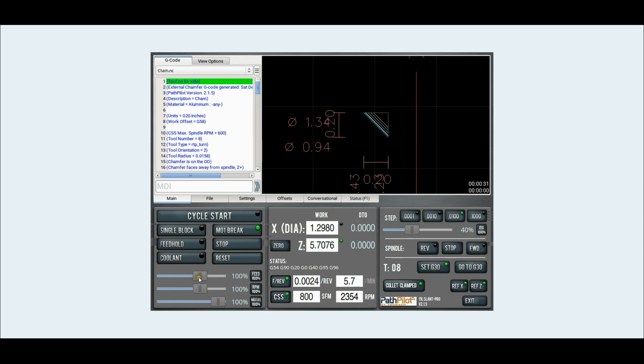So the feed is the actual cutting speeds and such. A lot of times I'll drag that to 0. I'll drag this down to 2% or something when it gets close, and then it'll basically just stop. Once it finishes the rapid move in, it'll just stop before it starts feeding in, because the feed will be set to 0. That way I know that everything's fine, and I can easily drag this to 0, just like a tick over, to stop the machine from hitting the spindle if it's too close. Once it stops, then I can easily hit feed 100%, and then it'll kick off and start cutting again.